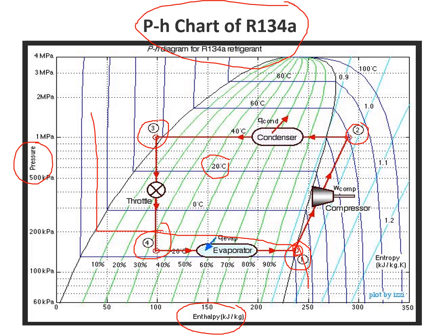You see, you measure the pressure somewhere here. So this is the pressure line, this is the temperature line. Where that will cut, that will give you the state 1. It may sometimes be the superheated region also. That depends on what the temperature and what the pressure is. So its intersection will give you the state 1.